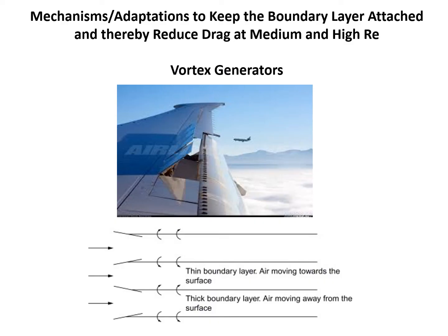So one way to prevent that boundary layer separation and that reverse flow, or that unfavorable pressure gradient, is, as we've already seen, to generate turbulence. And one way that was shown in the movie was a tripwire that generated turbulence. So if you disturb that laminar flow, it can generate these small vortices, and that turbulence in the boundary layer then helps to keep the boundary layer attached. And that's what you're seeing here.